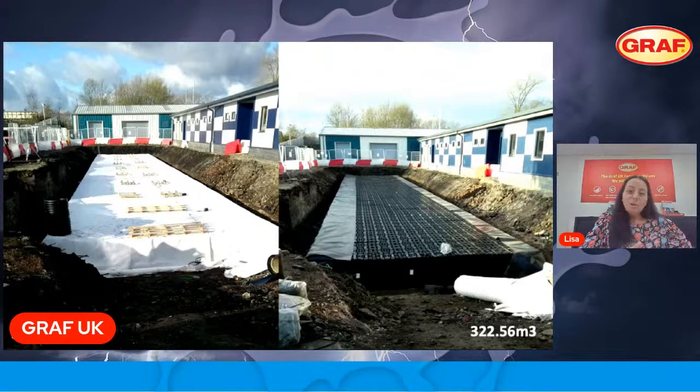It was really good as well because this tank was initially designed as an L-shape tank. Because of our crate dimensions and our void ratio on this one, we designed it, value engineered it, in such a way as to eliminate the dog leg, the L shape. And it worked perfectly with our EcoBlock Flex Inspect, creating a nice, clean, easy to install rectangular tank. So we saved the customer quite a bit of money on that compared to others. I think they were very, very happy with it.